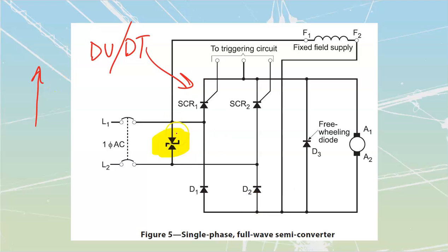So we've got this inside here. That's just going to be a filtering element. It's connected directly across line to line, and it's designed to pass only the high voltage section, stuff that's over top. It's based upon a value of voltage and upon this speed that it's going to have, and it's just going to pass those through. Any little blips that we get off of the system get passed and filtered out of there.